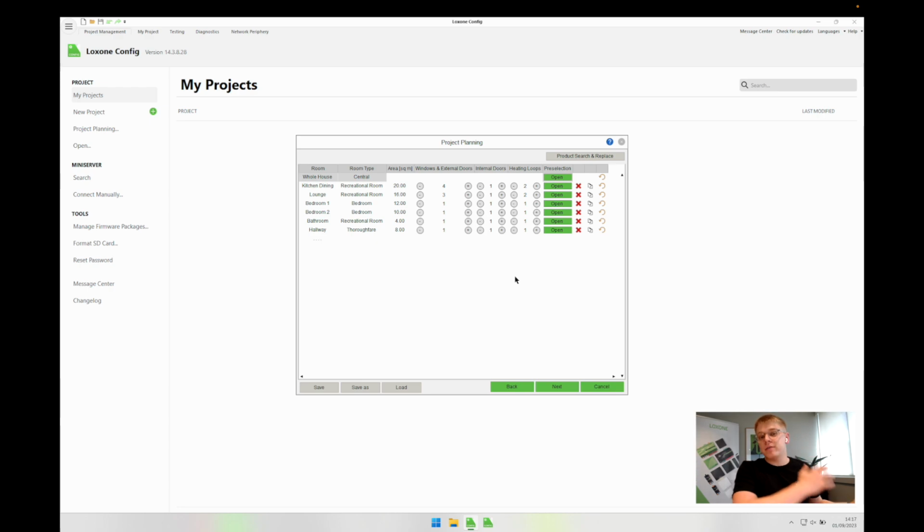It's unlikely they will have a light switch for outside as a point of control. It will either be automated or via the Loxone app. Therefore, keeping it in one room in the Loxone app means fewer steps and fewer taps to access these features. So I'm going to create another room and call it outside. This is other because it doesn't come under any of these other categories.